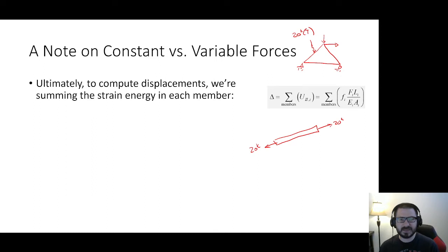So it's 20 kips in tension, and it's 20 kips everywhere. It's 20 kips here, 20 kips here, 20 kips here. It is experiencing a constant force along its length. That axial force of 20 kips does not change, because that goes into the assumptions that we use when we analyze trusses in general. Remember, when we analyze a plane truss, we assume frictionless joints. We assume that the loads are applied directly at the joints. We assume that the centroids of the members coincide. What that means is that the members are only carrying compression and tension, and it's constant throughout their member length.